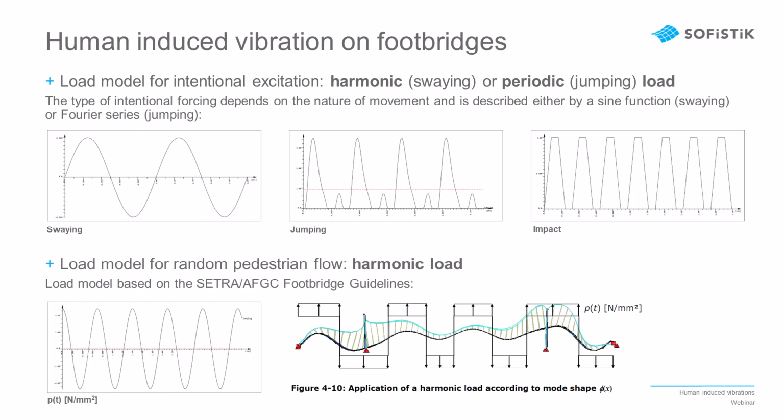All the previous considerations presented so far account for dynamic effects induced on a detail level, and might not be practical to simulate the impact of a daily random traffic or larger groups that could be expected on the bridge's opening day, for example. The French CETRA Association has proposed a loading model that has become widely adopted since.